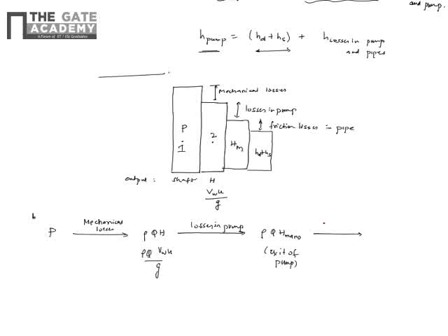And then you have the friction losses in the pipes, all that, FLV square by 2 GD, for the suction and the delivery pipe, friction losses in suction and delivery pipes. And what you get at the outlet is your static head, your change in the height, rho Q into change in the height. So this is static head.